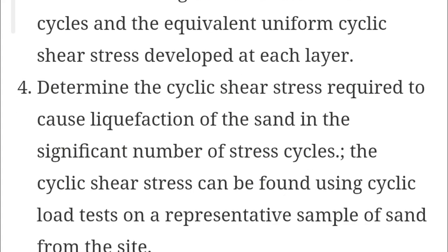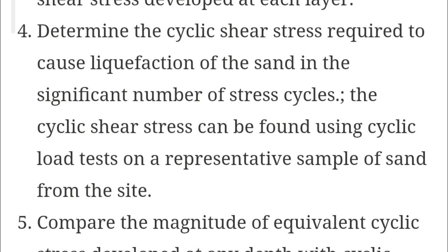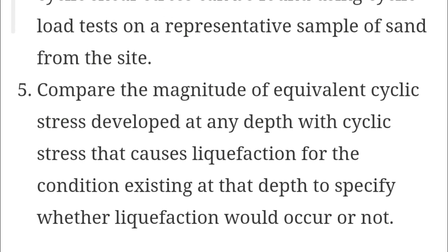After that, we can determine the cyclic stress required to cause liquefaction of the sand in the significant number of stress cycles. The cyclic stress can be found using a cyclic test on a representative sample of the sand from the site. Finally, we compare the magnitude of equivalent cyclic stresses developed at any depth with the cyclic stress that causes liquefaction for the condition existing at that depth, to specify whether liquefaction would occur or not. So this is another method we can use to find the liquefaction potential in the field.